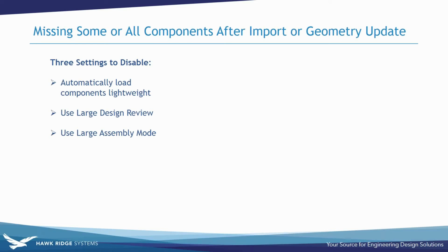When opening SOLIDWORKS CAD files, Composer uses SOLIDWORKS as a background process to convert assembly and part files into an SMG file. As such, settings in SOLIDWORKS will affect the importing process for Composer. There are 3 settings in SOLIDWORKS that cause this issue, 2 of which are enabled by default after new installations.